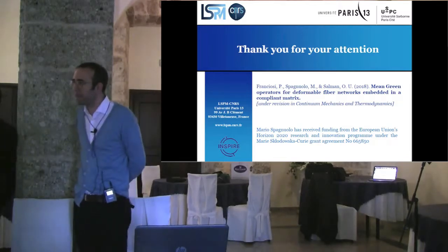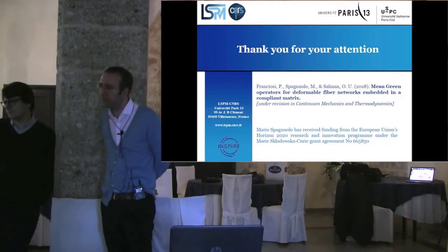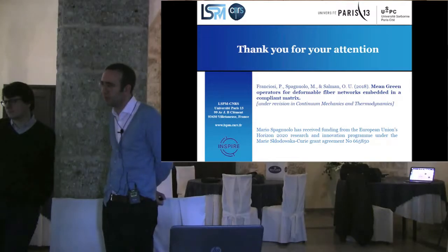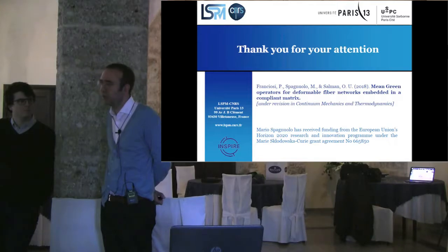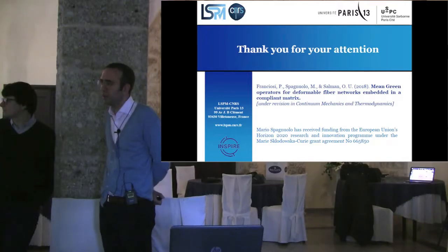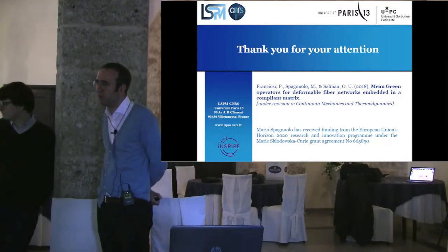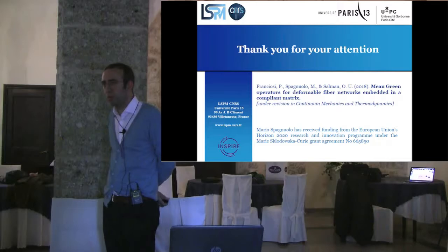Thanks. Yes, a physical comment. In fiber reinforced materials, you use bundles typically. If you make an experiment on bundles, you find that the mechanical properties of the bundle are quite different from the single fiber. This is due to the interaction, mostly due to friction arising between fibers, in this direction and the other direction. So when you say you account also for possible contrast between fibers, can you incorporate some effect of sliding and friction, which would be very important for matching results?